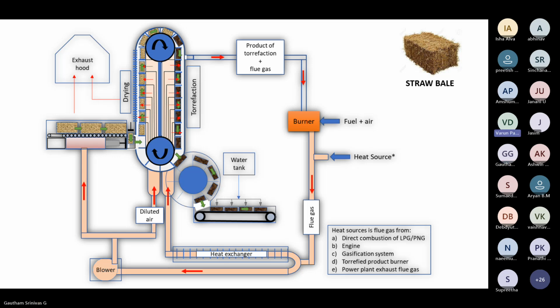happen? Yeah. So it will also contain oxygen, which might lead to its ignition there. Exactly. So that is the reason we are using the indirect method of heat transfer over here, which is a heat exchanger. And here we are directly mixing air with the flue gas.